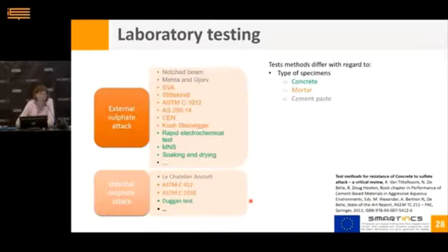So we normally want to know what is happening in concrete, but in a lot of cases in the lab it's more easy to work with cement paste or with mortar specimens. Of course, then you don't take care about the interfacial transition zone that is present in concrete if you use cement paste, but there also you can find contradictory results in literature on how important the ITZ is in that case. But you see some of the tests work on concrete, others on mortar, and others on cement paste.